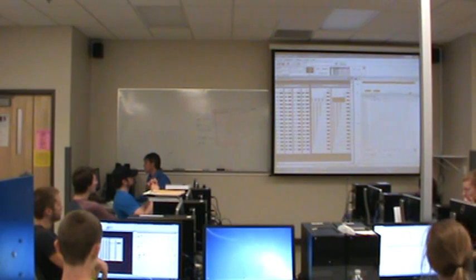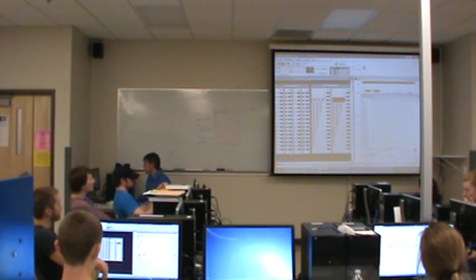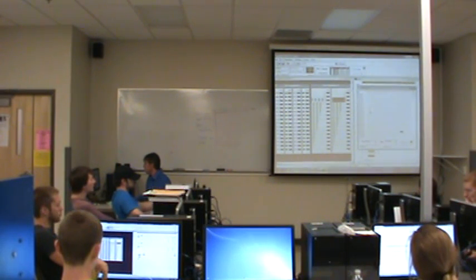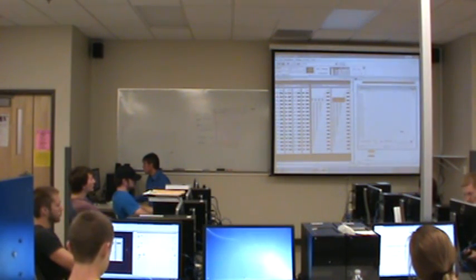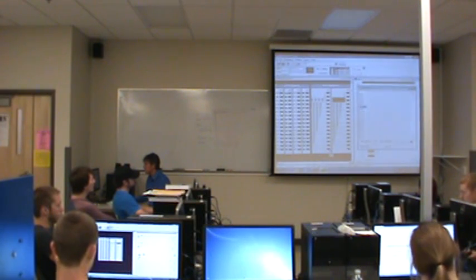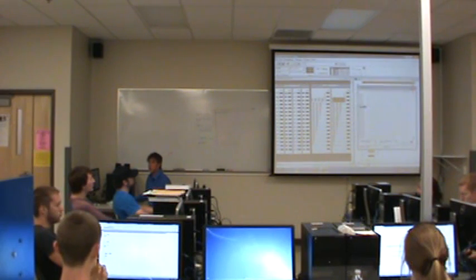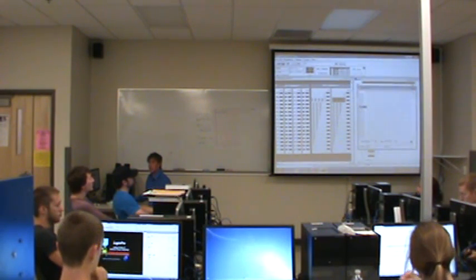So what do I have to do that? Well, let's find out. Incrementing this causes it because the next pattern that sequence compare was looking for was 001, 0001, 0001, 3 zeros again, 1, 0. That's exactly what I have now. 001, 3 zeros, 1, 3 zeros, 1, 3 zeros, 1, and a 0. So I was looking for that last bit pattern, and I didn't have room to add that in it. Kind of makes sense.